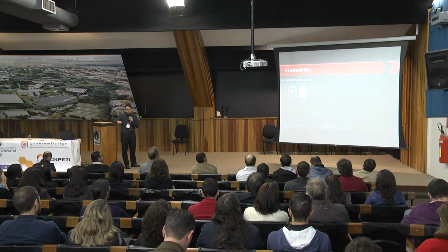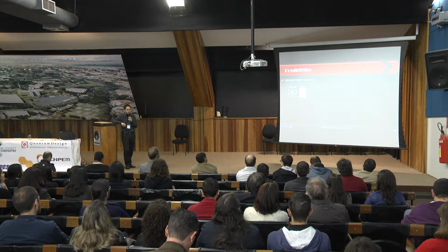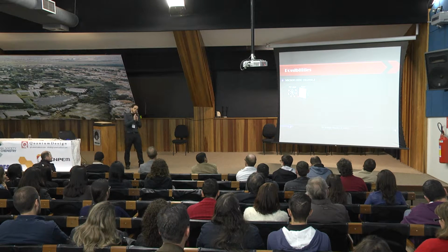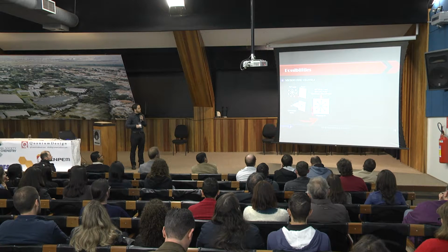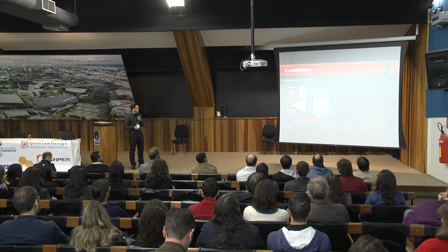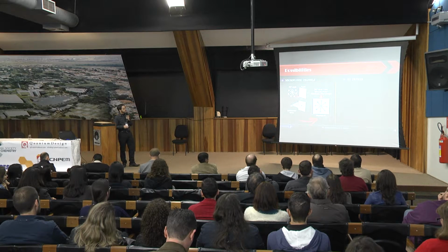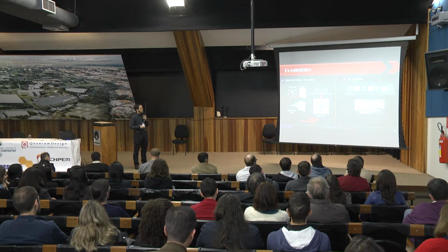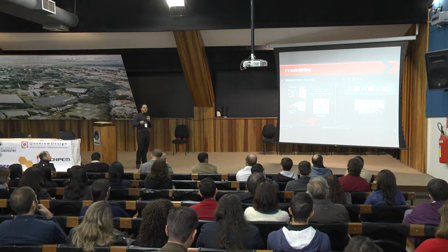So what else can we do with triboelectricity? In our laboratory, we also try to create microfluidic channels by using some PET masks. We charge the PET masks, put them in contact with the paper, and then we spray some hydrophobic ink and create the pattern. And that's actually a picture of the device that we fabricated with this strategy. We can also create 3D devices by using pieces of charged PET instead of double-sided tape.